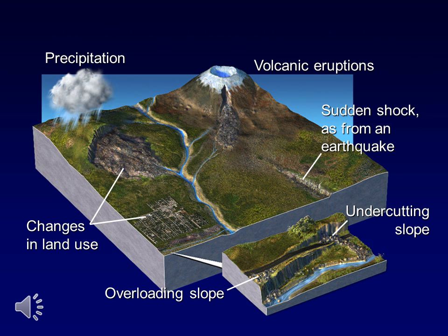Observing the different areas of this terrain, I'd like you to think about events that could cause slope failure. So we've got lots of examples around here. Change in land use could include deforestation, weakening the soil, or building towns that load the soil and change runoff patterns. Where water can puddle, that can trigger the expanding and compacting of clays, so that shrink-swell action of clay-rich sediment.